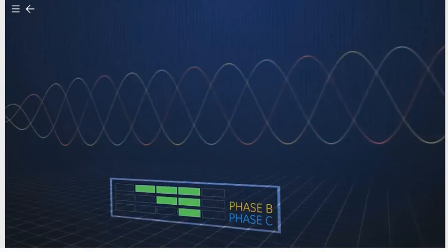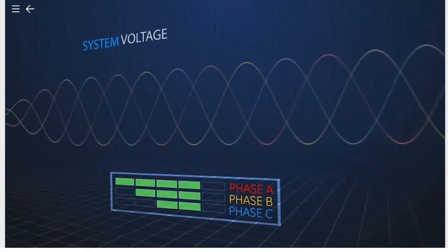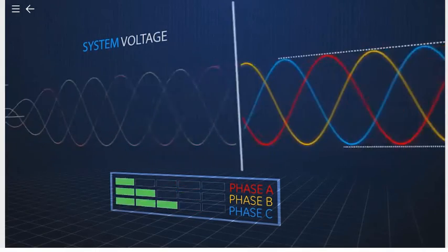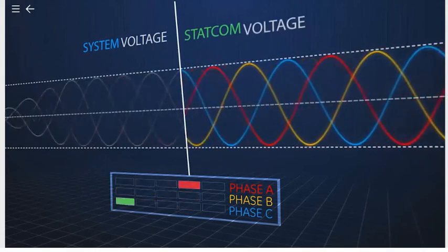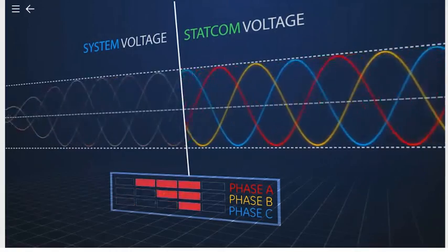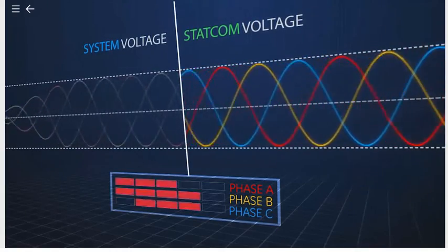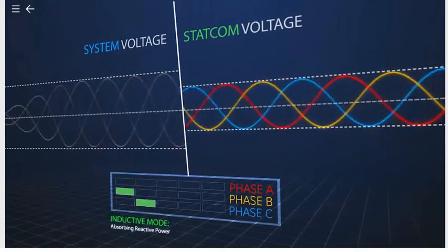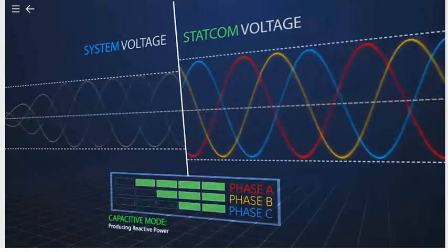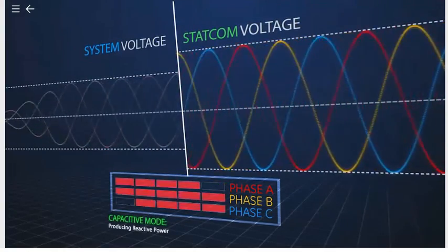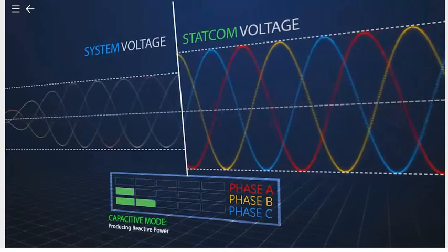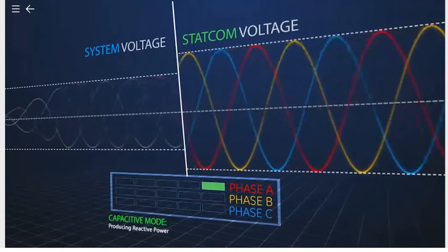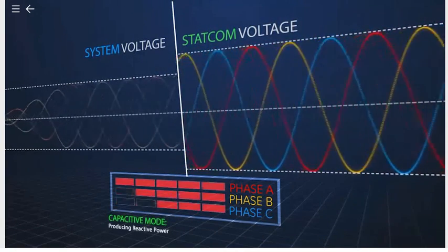The sophistication of the STATCOM is that it is continually monitoring the always changing system voltage to maintain its output relative to the changing input. Simultaneously, the STATCOM is rapidly providing either inductive compensation or capacitive compensation when required by the system. This complete process allows total control over system compensation and helps to maintain grid stability and boost efficiency.